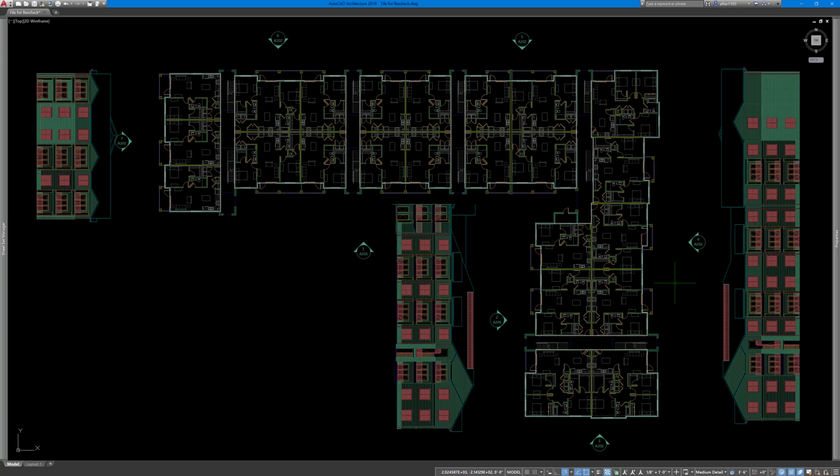Again, the thing that I see a lot of folks miss when they do these compliance checks is a lack of understanding what you are calculating. What the software is interested in is the conditioned envelope of your building. No more. It is not interested in the area of your unconditioned porches. It is not interested in the area of your unconditioned breezeways.